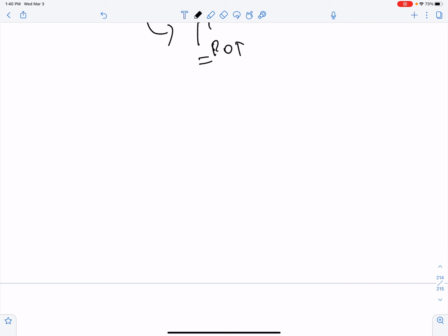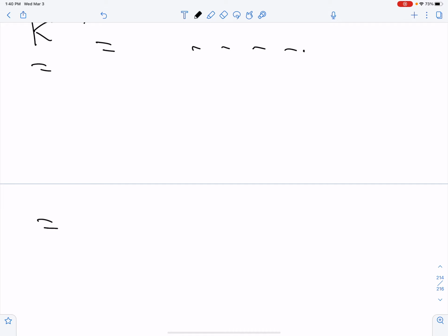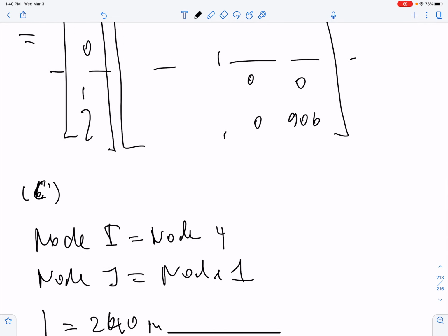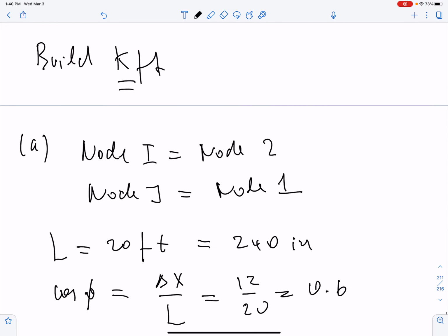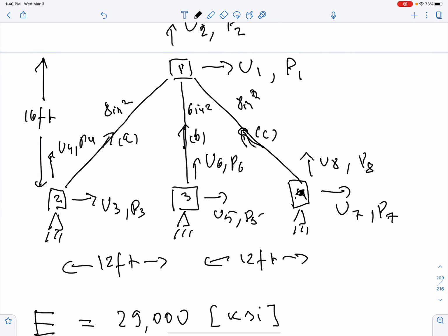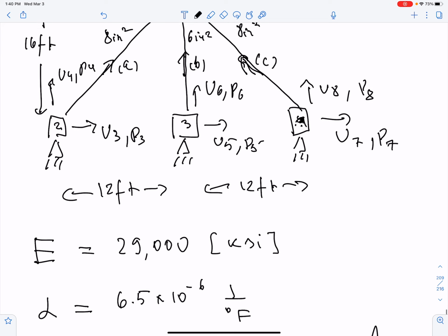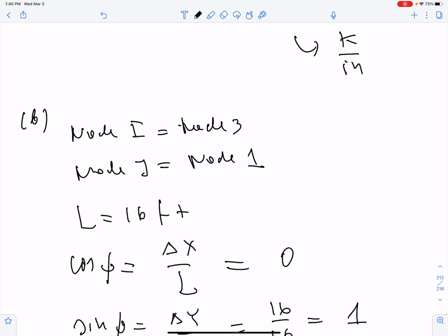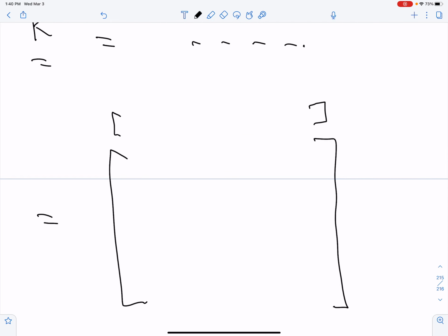Okay. So when building the matrix, okay, nothing new, use the usual expression, you come up with something that's 4 by 4, right? You put the ID array, and again, the way we set up our elements and our orientations is we start here. The two nodes are restrained, so 1 and 2 are restrained. 3 and 4 point to 1 and 2. That defines for you the ID array, which again happens to be 0, 0, 1, 2, okay?